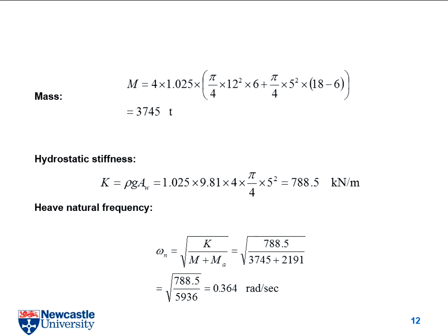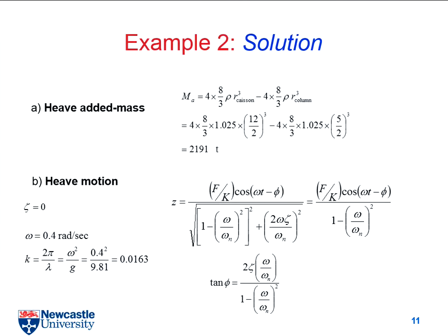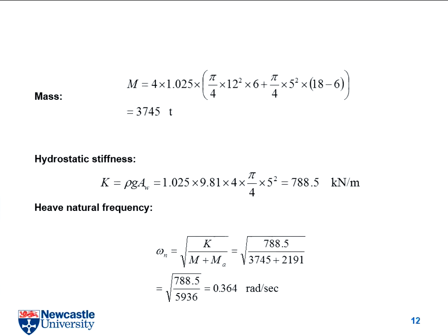So here it's from the calculation here. Here is your real mass. Here is your added mass. So by these 3 terms, we will know the natural frequency. So if we go back to the expression here, phi is 0. Now we know the natural frequency. We know what is stiffness. The last one thing is we need to find out what is the force in Z direction, and then we can just estimate the response, right?